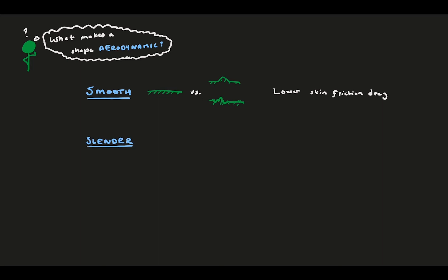Second, you want to be slender. Avoid changing shape too fast with respect to the flow. Otherwise, it will separate and your performance will plummet. Specifically, you want to avoid closing your shape too fast. It is the flow expansion at the back end that leads to separation.